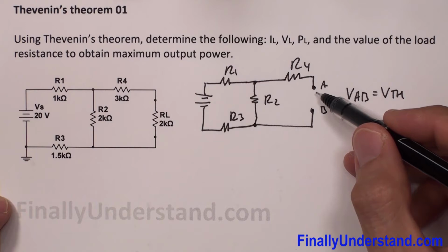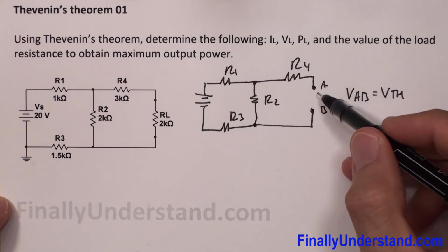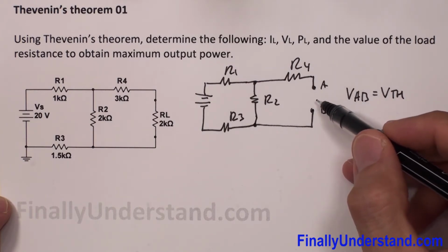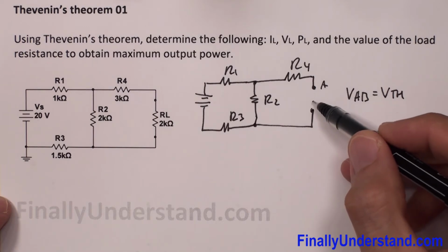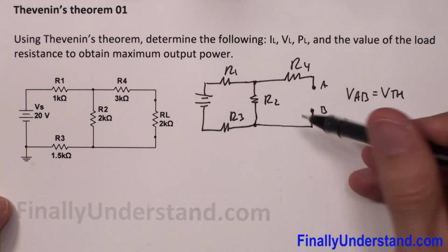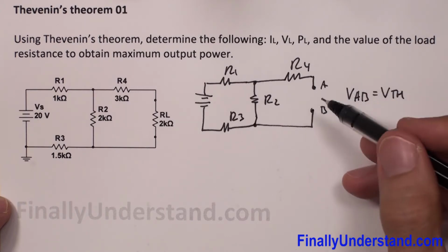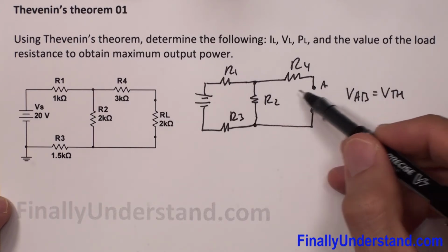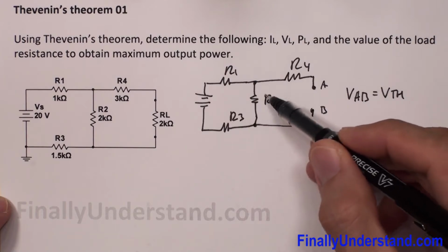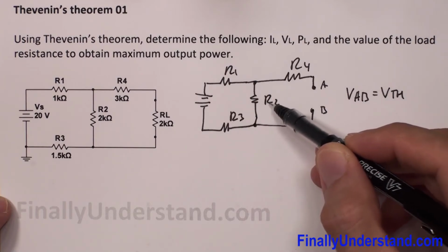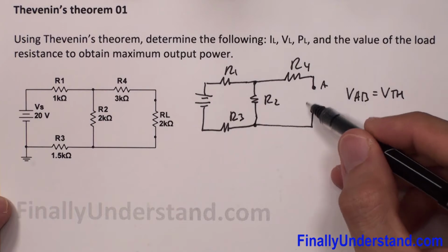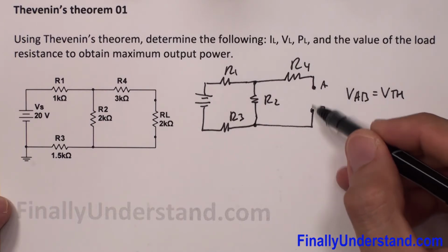Also keep in mind that the highest voltage is always going to concentrate across the highest resistance. So if this is the highest resistance between these 2 points, because air has very large resistance, the voltage which will occur across resistor R2 will also appear between these 2 points.